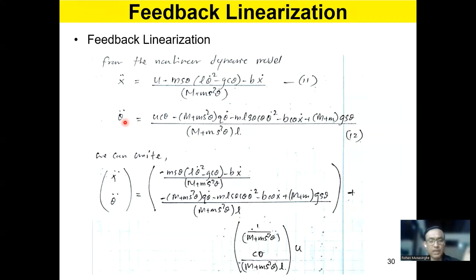Now we are looking at the other side. First of all, we will write these two equations, x double dot and theta double dot, as a matrix equation, and then take this u and this u cos theta. These terms are the external input to the plant, the control signal. So we will write these two terms as a separate term here. This is the autonomous system, which changes on its own, and then this is the external part, the exogenous control.